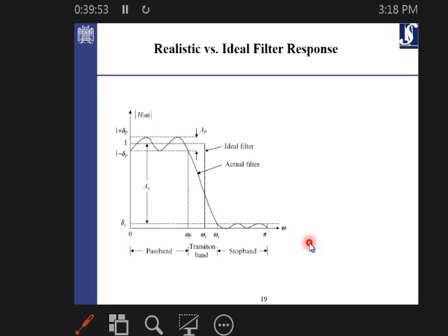For the IIR filters, we never have gain. In the analog design, the maximum is always bounded to 1. You will never exceed 1. In the digital IIR filter design, you can even have more than 1. You can have a gain. Even for the FIR design, you can have a gain. That's one of the other advantages of digital versus analog filter design. You can have a gain.